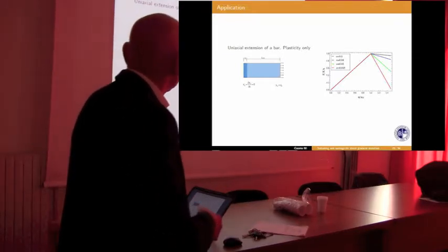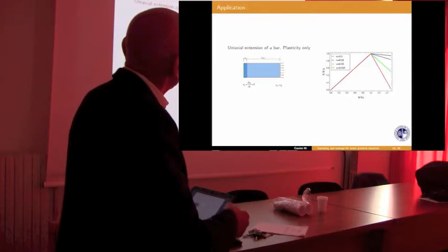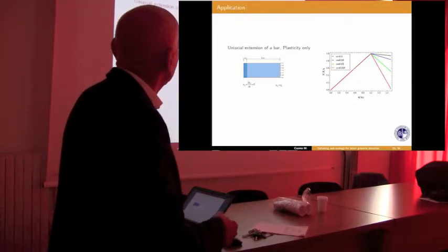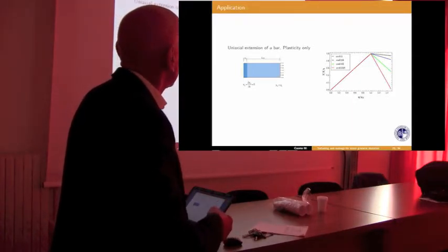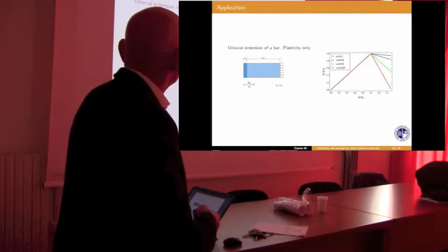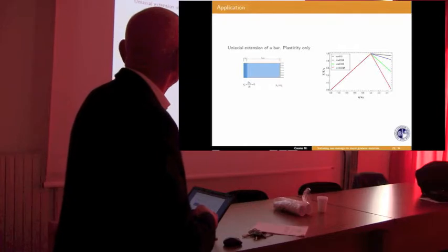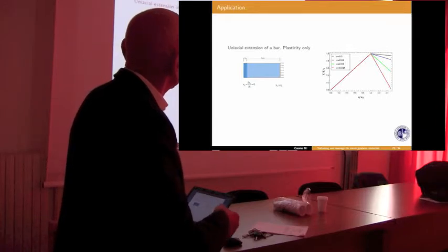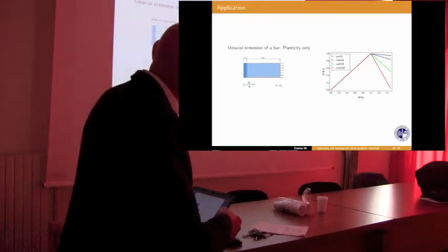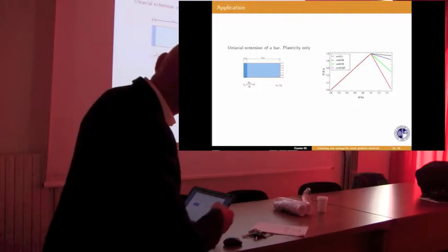This is in the case of plasticity. This is the solution with the first gradient deformation only, and it is seen that everything is homogeneous. In order to have plasticity, you need to introduce a small defect. But as the defect becomes smaller and smaller, this solution goes back to the elastic branch.